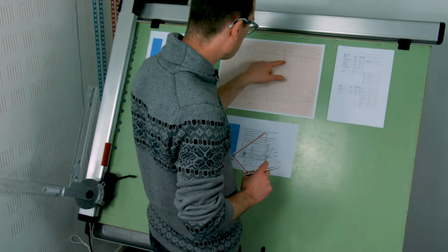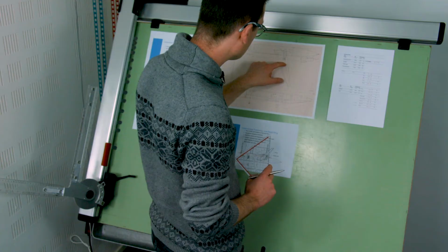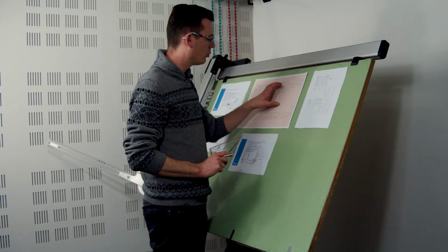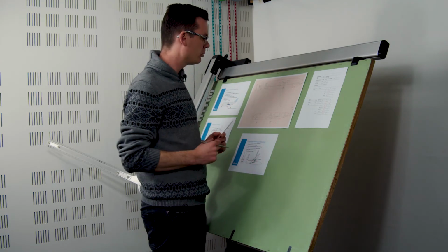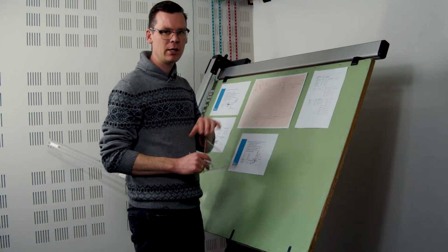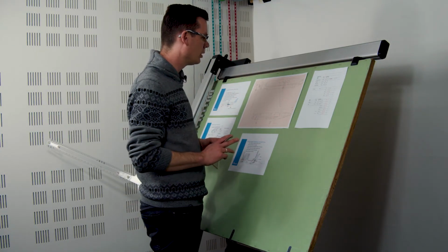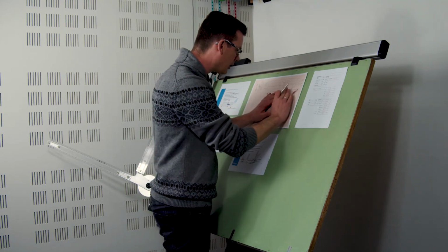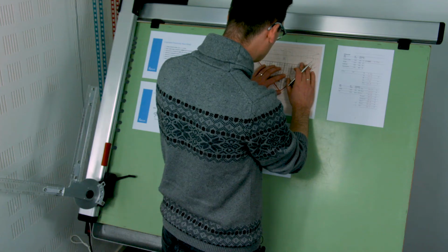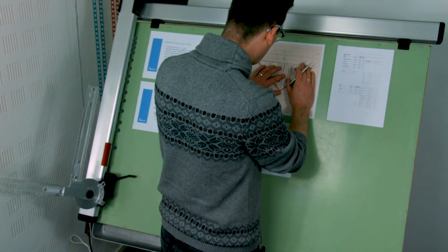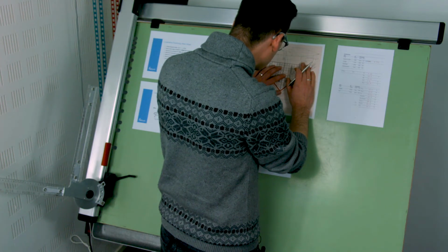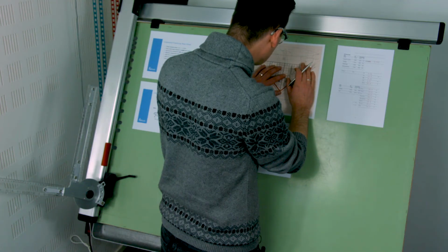And you can see if we put an additional spar there, we are actually interfering a little bit with the wing. So what we will do is add a kink to the wing. You can see that the integration of the undercarriage requires us to also make modifications to the wing. So that's what I'm going to do next. I'm keeping things constant from the intersection point onwards of the rear spar and the auxiliary spar. I'm measuring there a distance between trailing edge and rear spar of 1.2 meters.